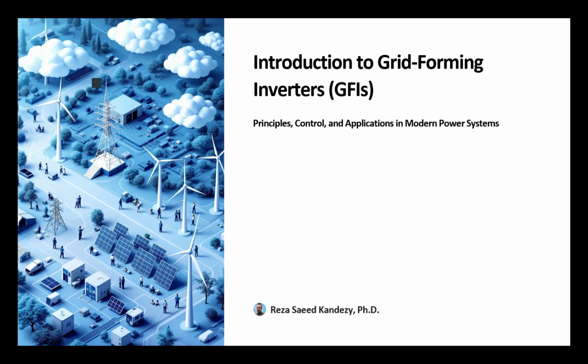And we said, okay, since the frequency is a critical parameter and we have to always be at the same frequency as the grid and we don't normally tolerate variation on that, we talked about the synchronization. If we want to have a grid following, we have to synchronize with the grid in order to keep that frequency condition met.